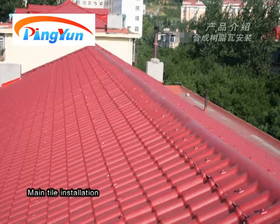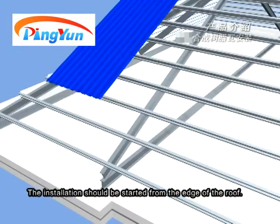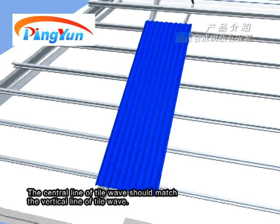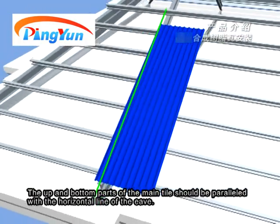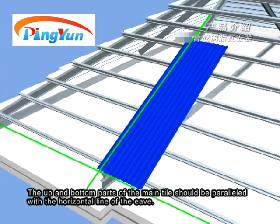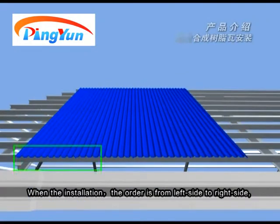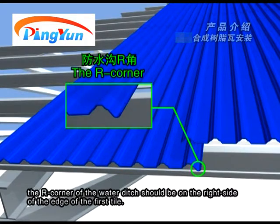Main tile installation on two slopes roof. The installation should be started from the edge of the roof. The central line of tile wave should match the vertical line of tile wave. The up and bottom parts of the main tile should be parallel with the horizontal line of the eave. The order is from left side to right side. The arc corner of the water ditch should be on the right side of the edge of the first tile.